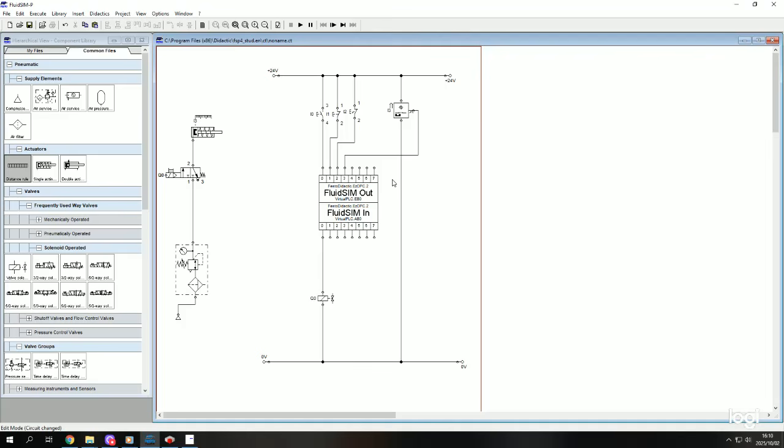Let me check the next exercise. That was exercise 2. So exercise 3, plastic pellets need to be filled from a storage silo. The silo is opened and closed with a flap. The process will be started from 2 locations. The flap is opened by pressing either one of the 2 push buttons, and the bulk material is emptied out of the container due to the cylinder advancing. When the stop button is activated, the flap is closed as the cylinder retracts.